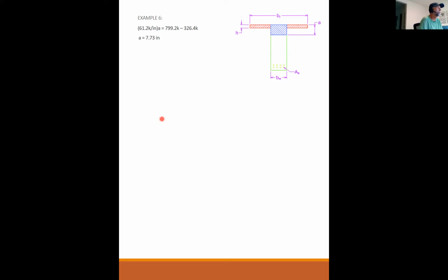And if it does act like a rectangular beam, the whole problem is a lot simpler. So you don't want to get into all this complexity first and then find out it was rectangular. I could have been done half an hour ago. So you always assume the simpler case first until you get to that step we just did where you prove that it's not.